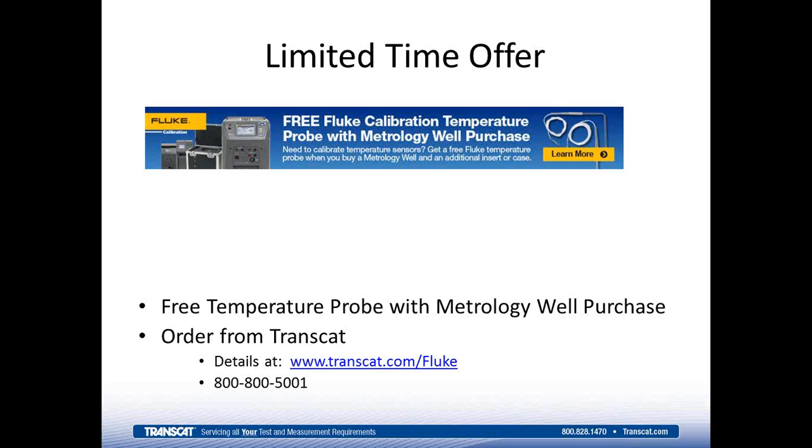Another tool you can use is to shorten the calibration interval for a couple of times and see how the probe is behaving in the environment that it's used in. If it's not moving around much, it's not drifting, and it's pretty stable, then you could consider lengthening that cal interval. So unfortunately, there's not one solid answer for that question. But if you'd like to discuss it more, you're more than welcome to give me a call and we can talk about it some more.